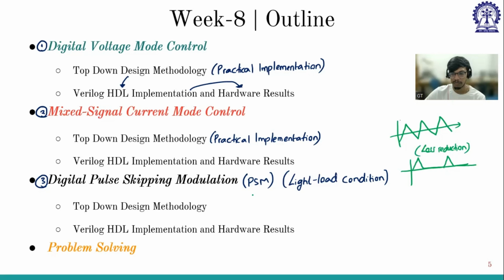Sir will discuss PFM in the upcoming weeks when he discusses the variable frequency modulation technique implementation in Verilog. But as this week is only fixed frequency, we are going for a fixed frequency light load modulation technique, and one such is voltage based digital PSM. We are discussing that, and then we'll see the Verilog HDL implementation, how to write the code, and hardware results.